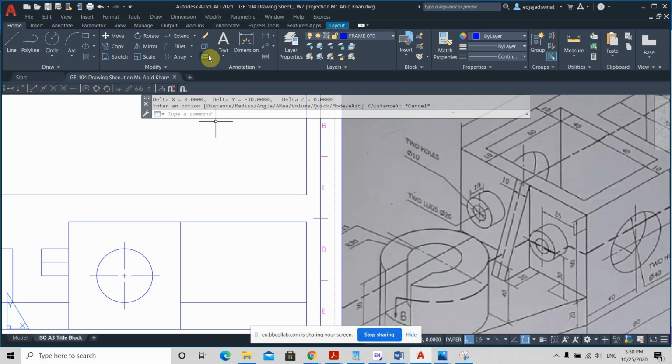So I can do offset. The small cylindrical hole is 5 milli in radius. So I do this, set there. Okay. So this is a hidden line. Again, we are talking about the front view, the original front view here. And actually, be careful, it doesn't stop here because now it's only up to this region.